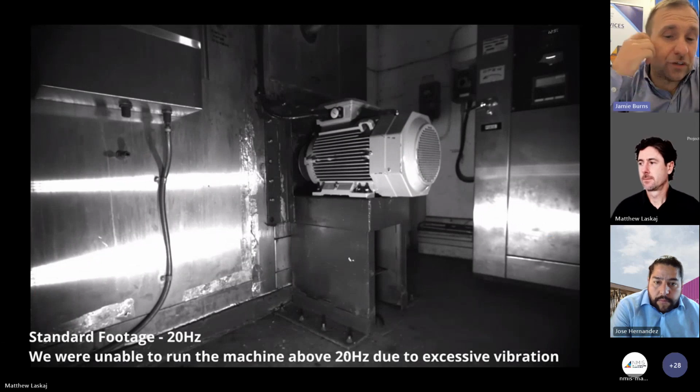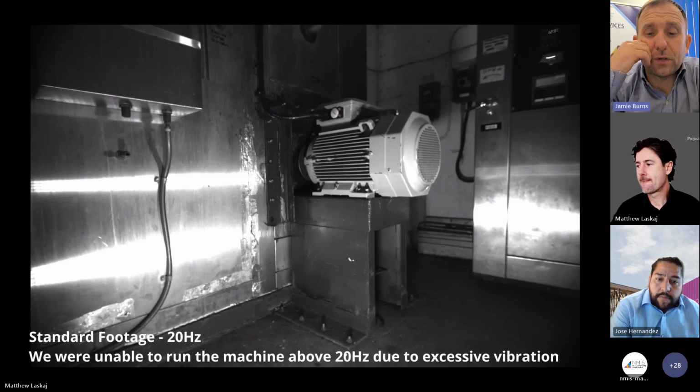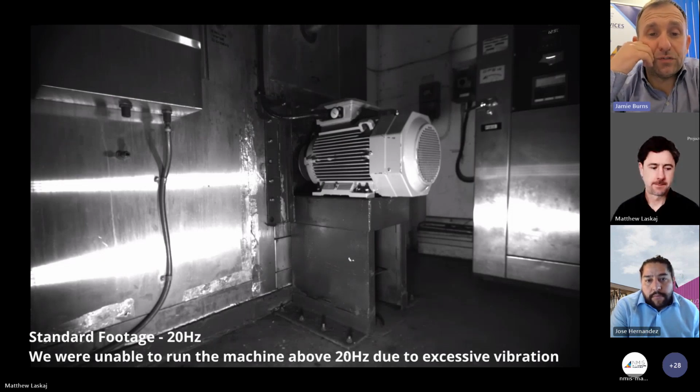So the machine itself was vibrating so much that we couldn't even run it up to full speed. It was shaking itself around so much that we think 20 hertz was as much as we actually put it up to. So we knew straight away that it wasn't just the balance, it was obviously something else going on there, because the levels of vibration were horrendous.